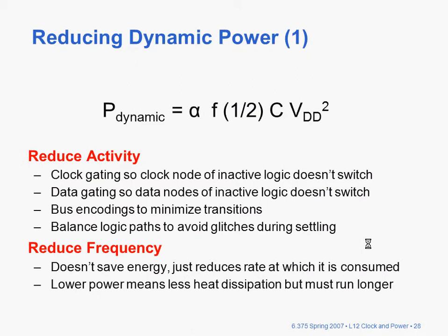So, reducing the dynamic power. We've already mentioned some techniques that can be used. Clock gating, so the clock node of inactive logic doesn't switch. Data gating, so data nodes of inactive logic don't switch. Bus encodings to minimize transitions, and balanced logic paths to avoid glitches during setup.